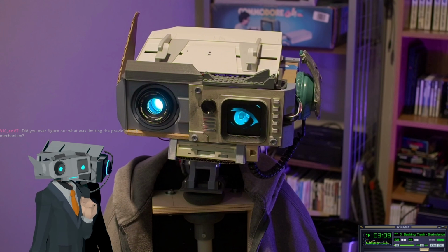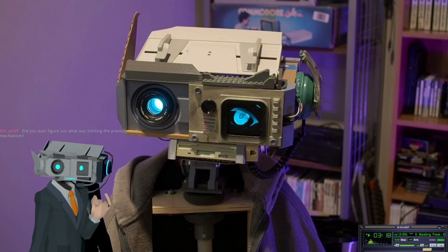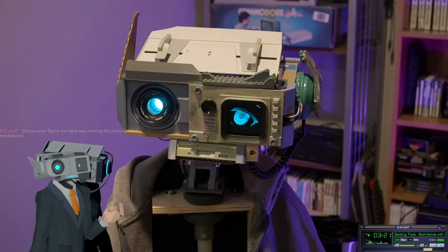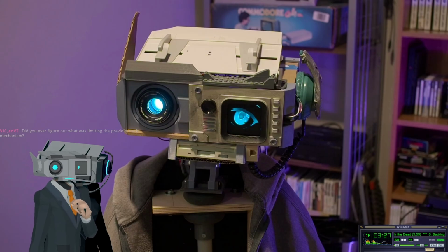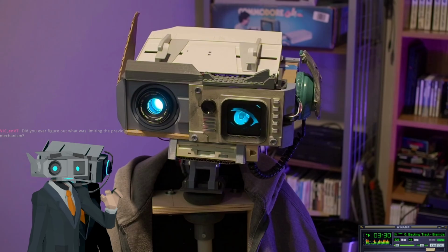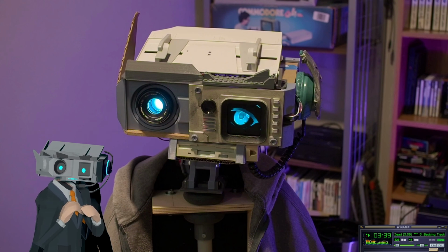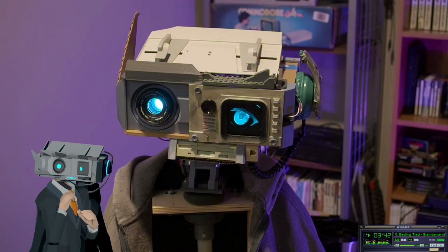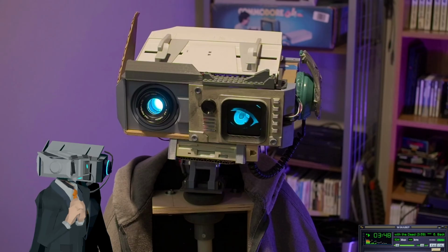He's a little forward heavy, and so my old neck, and partially this one, it's kind of off by design, off-centered by design. That way it'll be less wobble. It's called a backlash because I'm using gears, and the gears aren't perfect, right? They go together very well, but they're not perfect. So I made sure there was a little bit of weight on there to kind of make sure it wouldn't bounce around all the time. Not the best design choice in the world, but